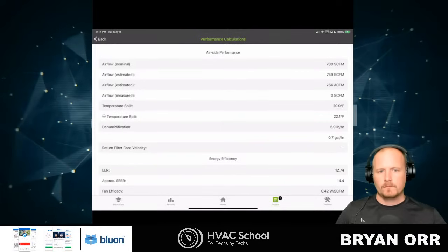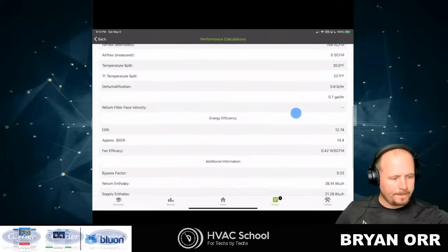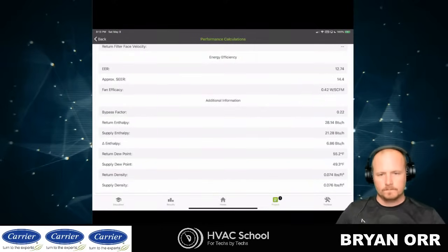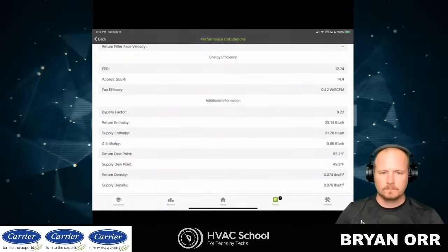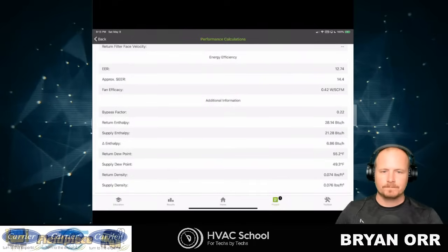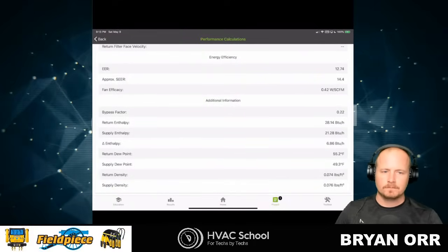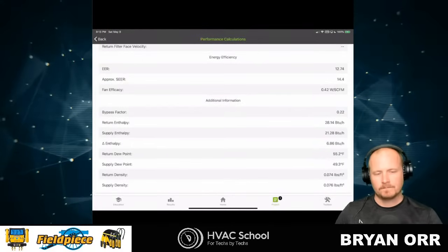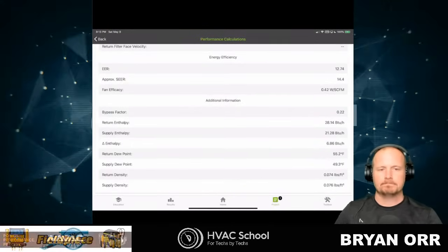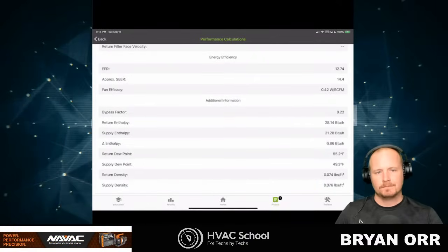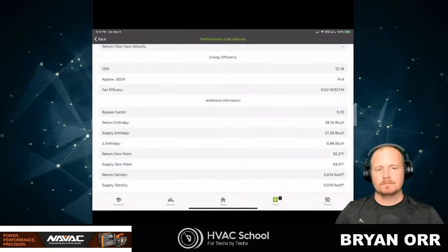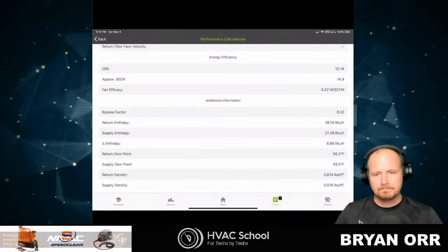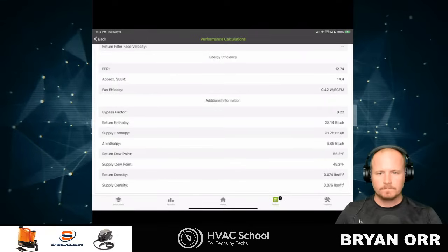But if you scroll down a little further in there, Brian, and there are some footnotes, you'll see that there are air density calculations. And so with an ECM motor, what will happen is you'll move more actual CFM when the air density is low to actually achieve the standard CFM that we need across the coil. It's quite cool when you start understanding all this stuff, because we really don't cool CFM of air, we cool pounds of it. And MeasureQuick takes all those things into account.